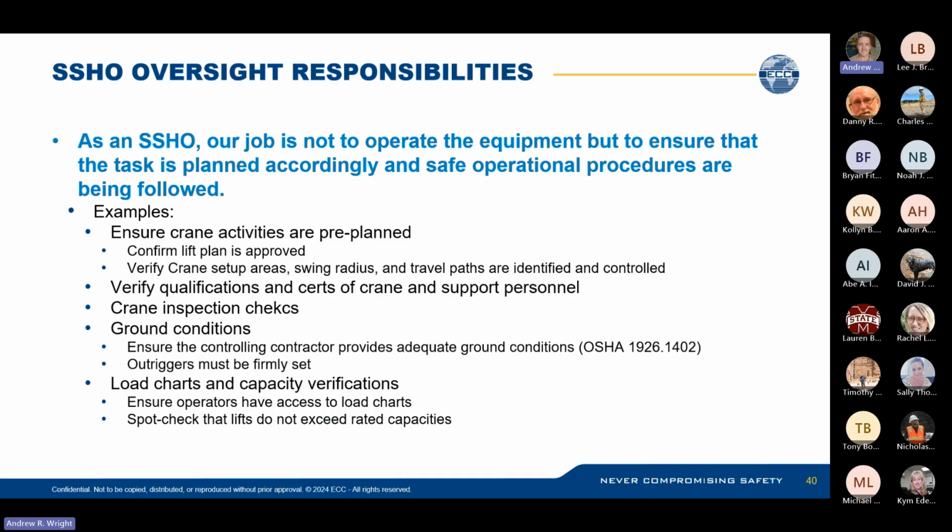And every now and then you're going to want to do a spot check and ensure that the loads do not exceed the rated capacities. If you are under the understanding that they're going to be lifting single sections of, say, structural steel members, and now all of a sudden they're lifting multiple ones, that should maybe raise a red flag, especially if they have been planned for doing tandem lifts or multiple lifts. You should throw up the red flag and ask a question at least.